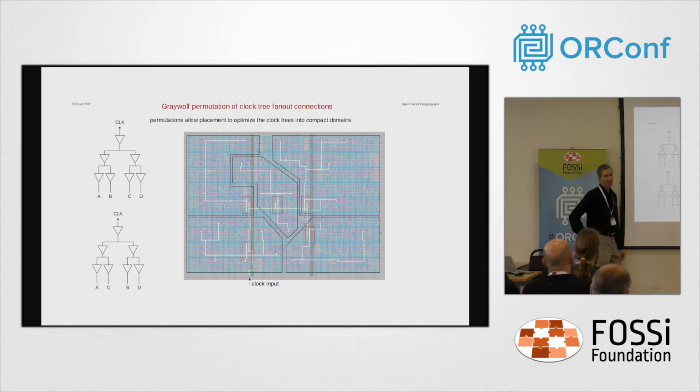Another thing that this does that I'm pretty sure Yosys doesn't do, but Clifford is always surprising me with what Yosys does do, is clock tree insertion, which is a big problem when you're doing a full chip design like this. And this needs to be a combination of a solution in your placement as well as your routing. If you have an FPGA core, it usually has a clock H-tree structure already in place, so that if you put in your clock at this point, it will evenly distribute it out to all the places.